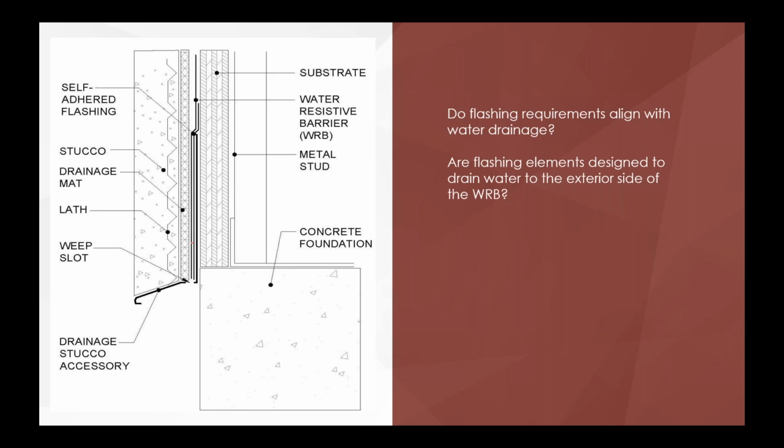I believe that the stucco accessories should always encapsulate the full system. Okay, what do I mean by that? So my leg is coming all the way back here, my attachment leg for my weep. This way it's going up against the substrate. And then this ground is probably going to be an inch and an eighth, an inch and a quarter to make sure I took care of my drainage mat. I'm forcing my water out through those holes right here, and my water gets out.